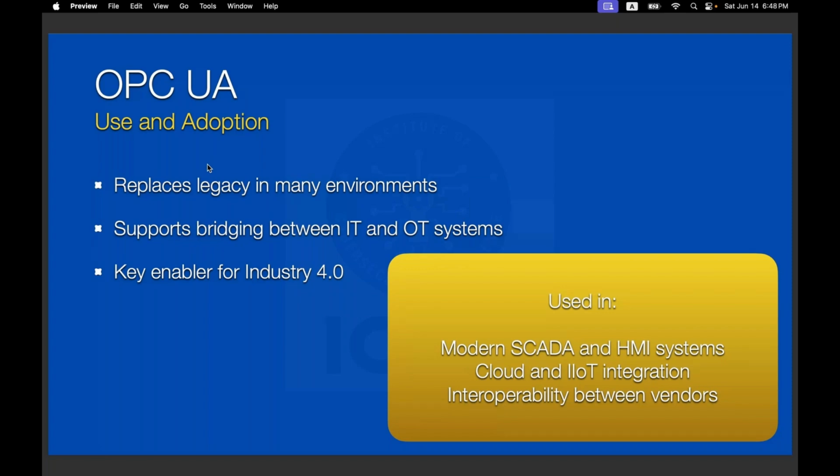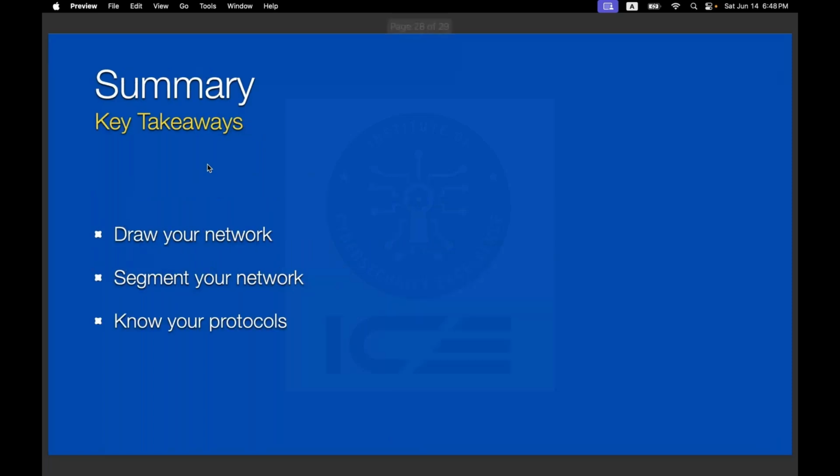And of course, we need to push to make secure protocols inside our ICS network, because otherwise, if you are trying to do micro or nano segmentation but have bad protocols inside, it's also not so good. As a summary, first draw your network physical diagrams showing where your devices are connected.